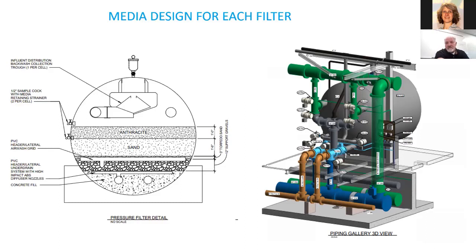And if one were to come back positive, we've got sites within five connections one way or another of that site, where you go upstream, downstream, and test for that. And then you would resample your site that failed to determine possible contamination or whether it was a false positive.